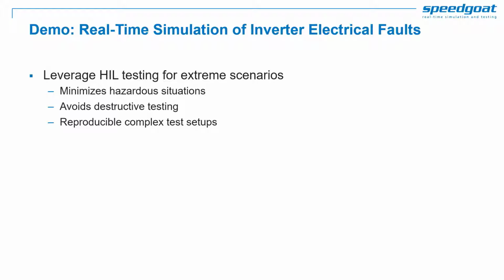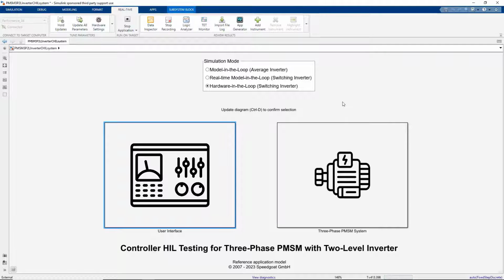Electrical faults are an example of a test that would be very difficult to execute with a real motor inverter drive, as it might compromise both the hardware and the test setup. Extreme precaution would need to be taken, as malfunction of the scenario at high power could have unexpected consequences. As the inverter model deployed in the template allows us to simulate electrical faults, it is very easy to observe the behavior of the current in such a case.